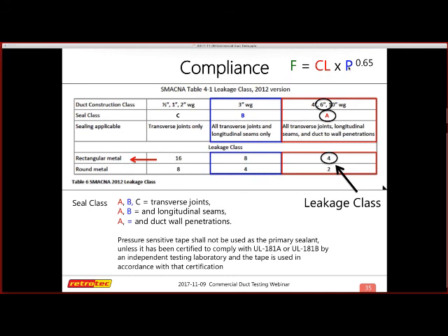There's a way to do this as the opposite too. But there's my 4 times 6 times 0.65, and there's my answer. So I'm approximately 13 CFM per 100 square feet. We'll make sure we understand some of these details.